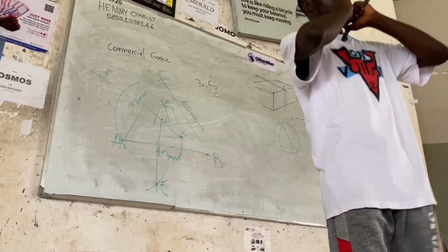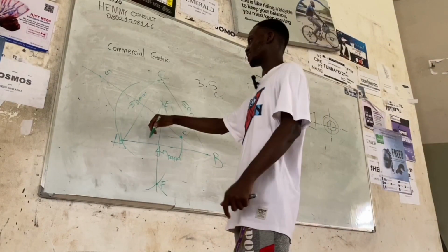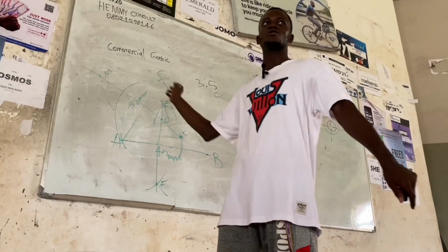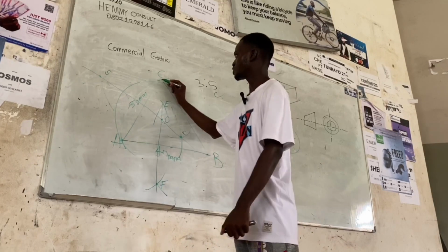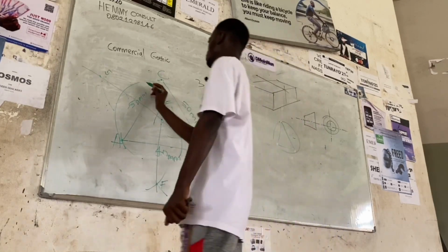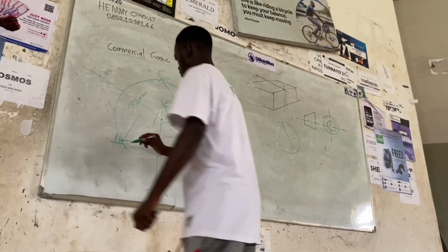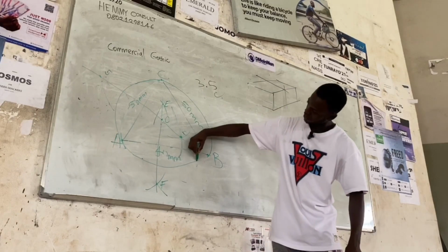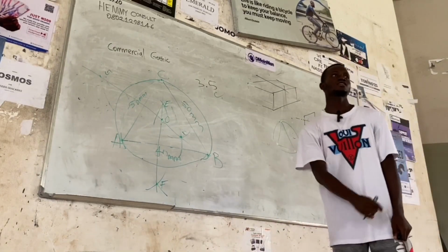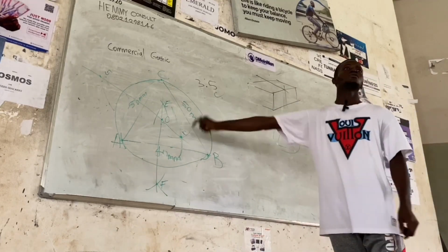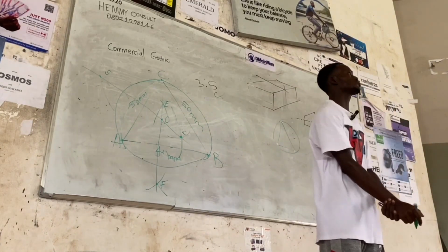No, I'm going to practicalize this so that you guys will see. I don't want the situation whereby you draw your line and it will enter one side of the triangle. The circle will intersect this point, and this last point. So it will be something like this. Something like that. So that's how you go about. That's how to draw a circumscribed circle to a given triangle.